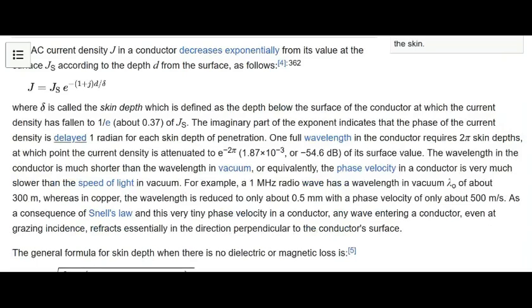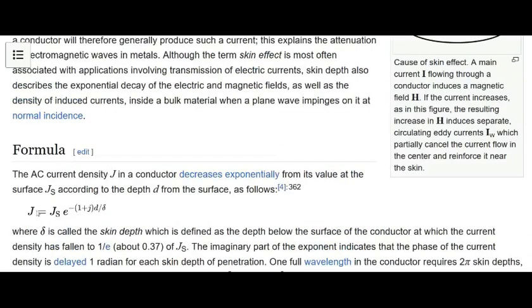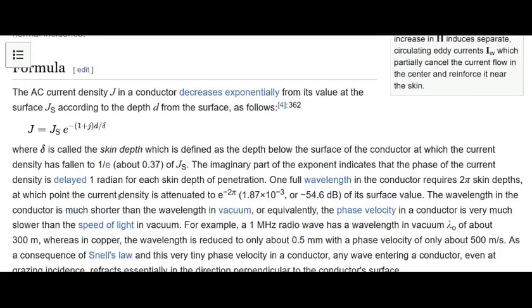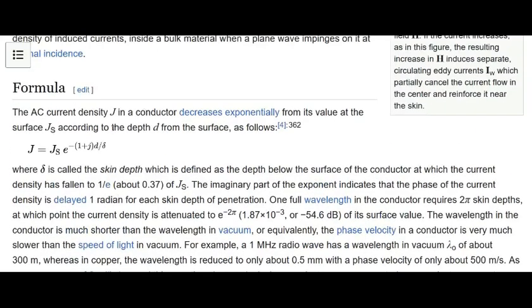And you know, we can calculate it here. They give us the formula. We don't need to, because we've got a continuously variable LCR meter where we can sample it at whatever frequency we want and read what the resistance is. And that'll give us both the decrease in resistance from the skin effect as well as the proximity effect.